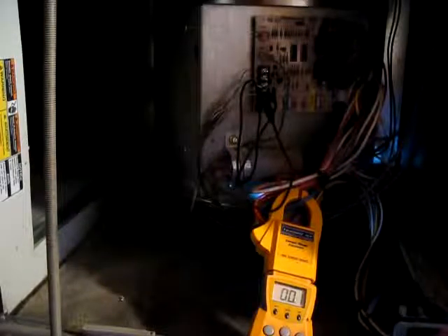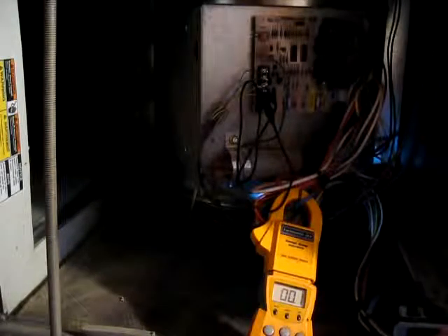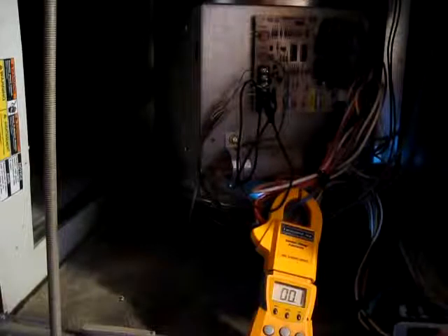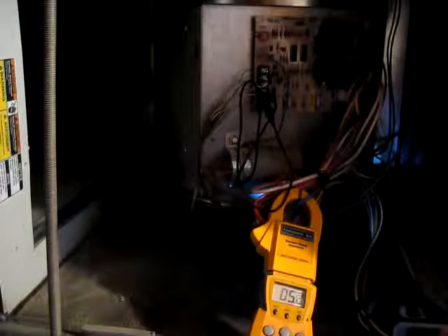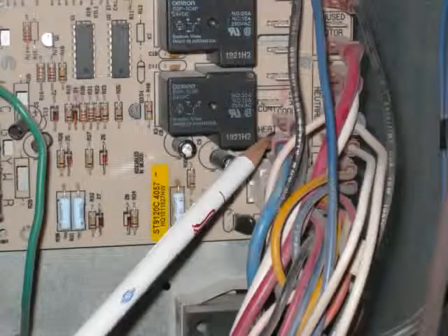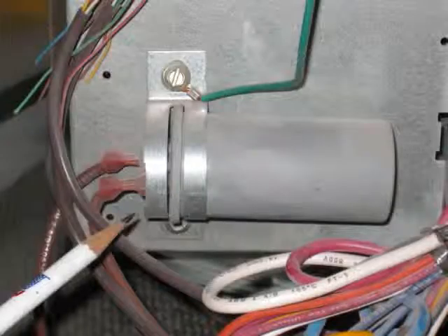Once the main burner is lit, it should burn for about 30 seconds before the fan turns on. The fan is turned on by the circuit board at a terminal labeled fan, heat, or low. This is usually 115 volts. If the fan is not turned on, you should check the voltage at this terminal. If you get voltage and the fan is not turning on, you have a bad motor or a bad capacitor. The capacitor is attached to the motor via two brown wires.